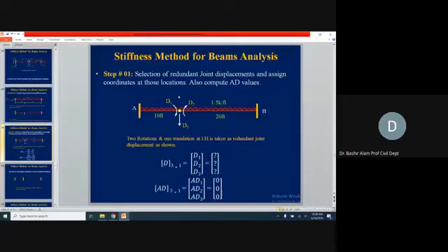A load of 5 kip was applied downward at this internal hinge, which was corresponding to D3, and it was in the same direction, downward, so then we include that 5. So here you will include 5. If we don't have, so we put this. So our ADL matrix is generated now.